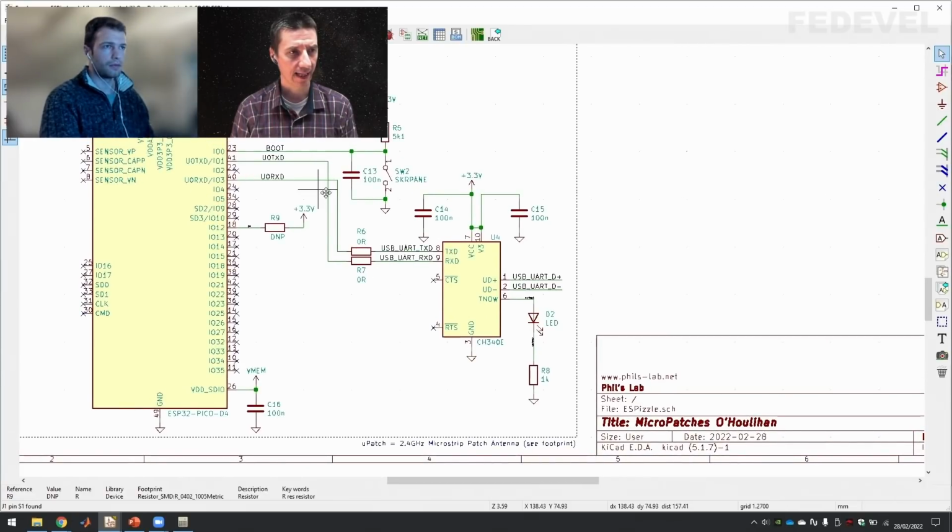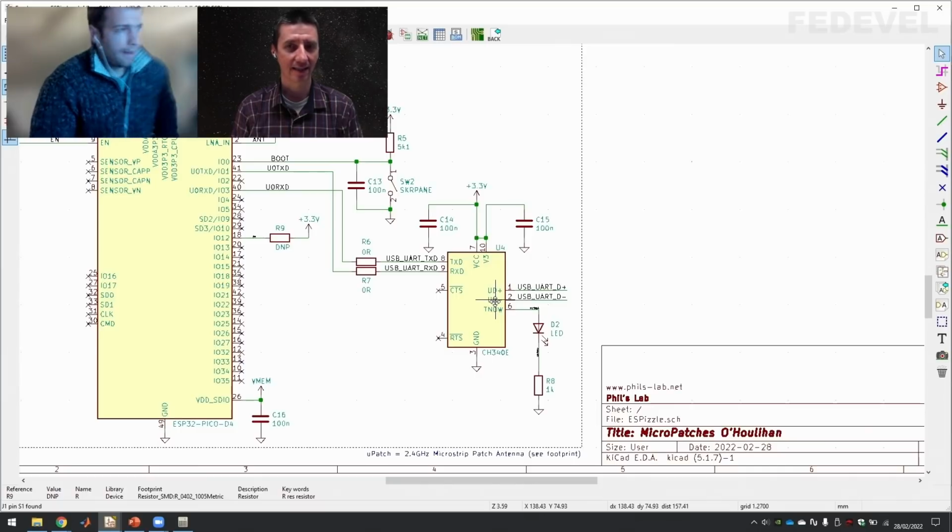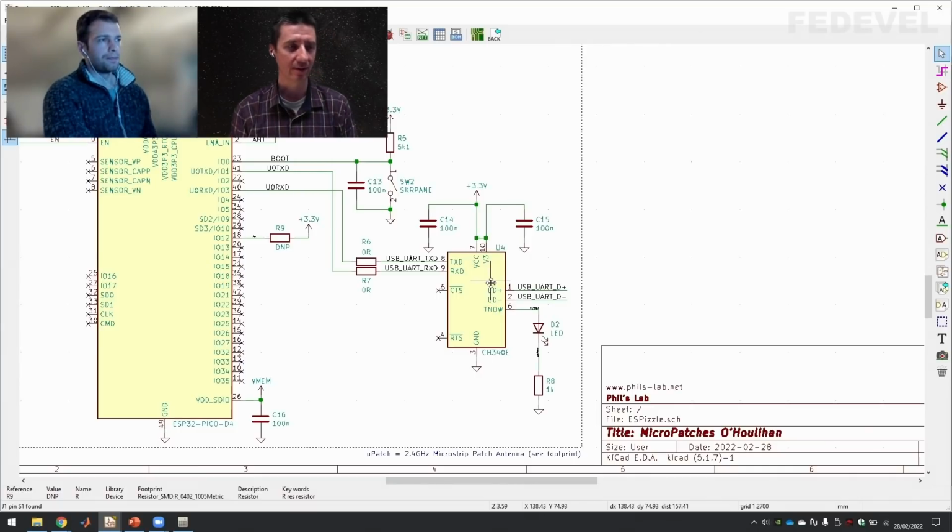When you say external driver, that's the 1K or no? What do you mean? Sorry, no, the actual host driver you need to communicate with a USB device. Ah, okay. So you don't use the standard FTDI driver, but their own driver. You get it off some dodgy site for this chip. At least that's how it used to be. I'm sure that's changed, but yeah, you can't use the FTDI drivers. So theoretically, you don't know what is inside of the driver. Exactly. It's probably stealing all your data and then sending it off via this great patch antenna. But yes, something like that.